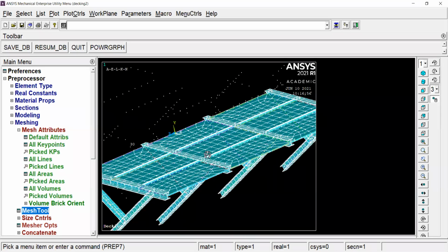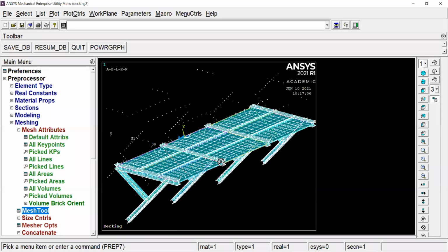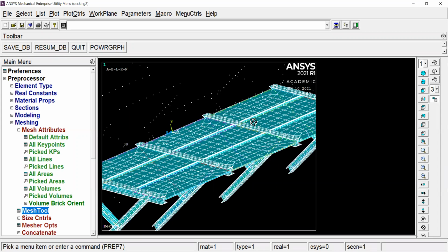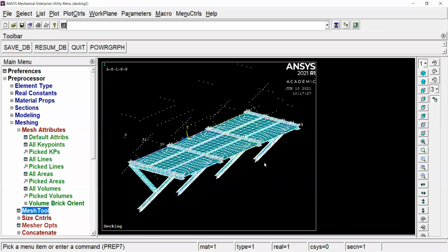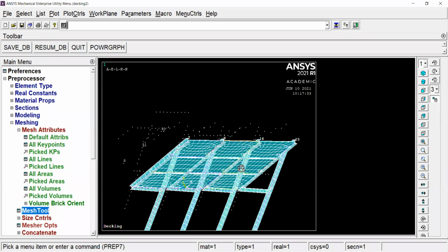Okay, the reason that it's not sitting on top of the beams is because we haven't applied an offset. But for all of your projects, you don't have to worry about offsetting beams or offsetting plates, because it just gets a bit too confusing at that point. So if they look like this, that's fine. It'll just mean that our beam is connected to our plate, but it won't say how it's connected, just that it's connected, and that's good enough. All right, guys. So I have a 3-dimensional model now.